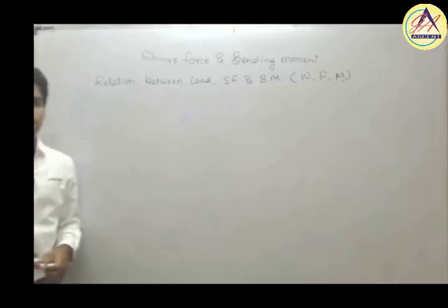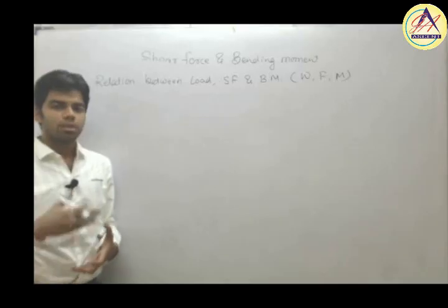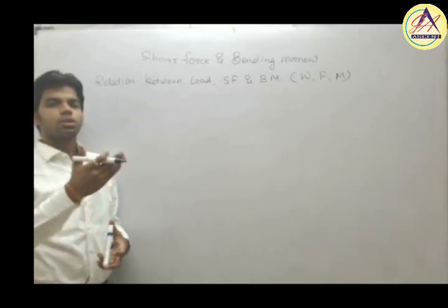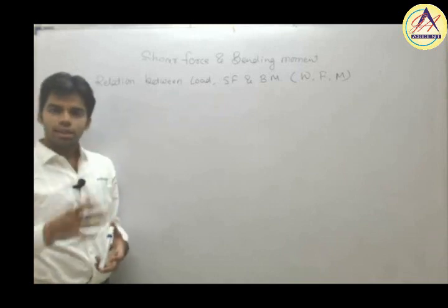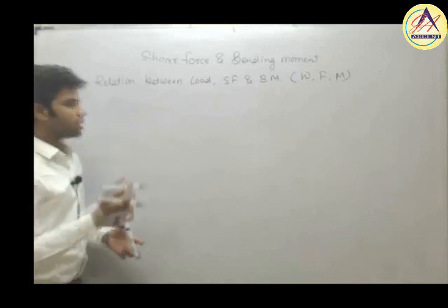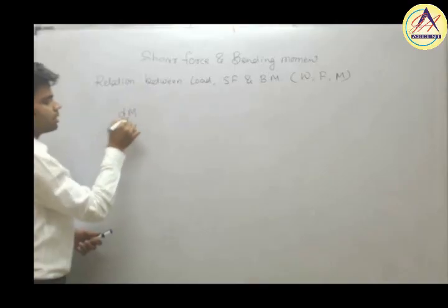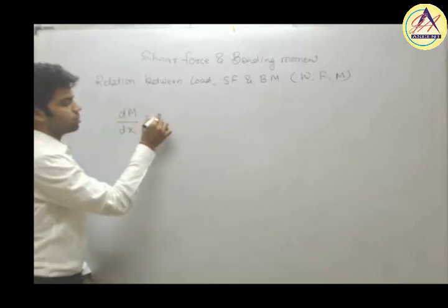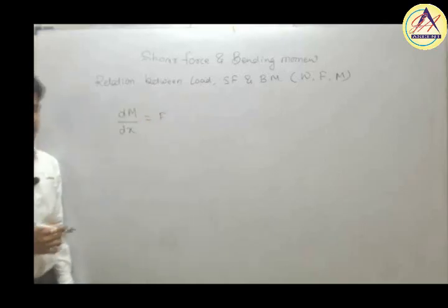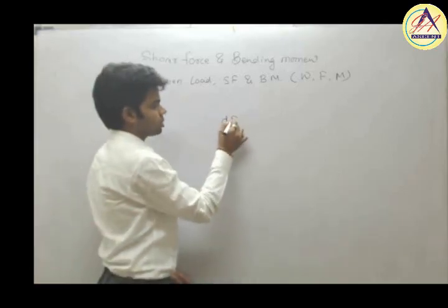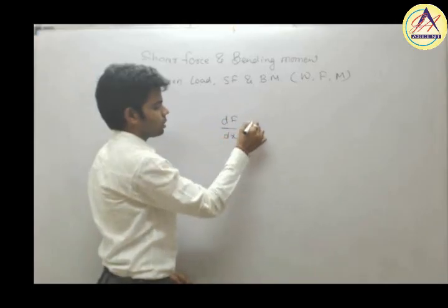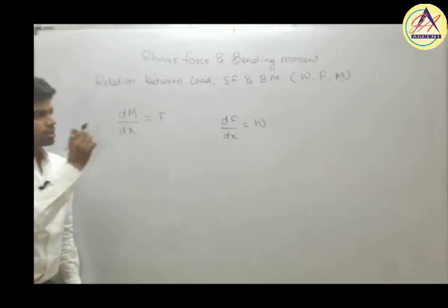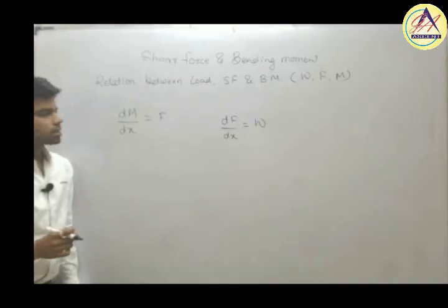So as we have seen, the curvature of the shear force diagram is one degree higher than that of the loading diagram, and the bending moment diagram is one degree higher than that of the shear force diagram. This means when we differentiate bending moment with respect to x, we will get what? Shear force. And when we differentiate shear force with respect to x, we will get what? Loading. Okay, now this contains an important conclusion in itself.